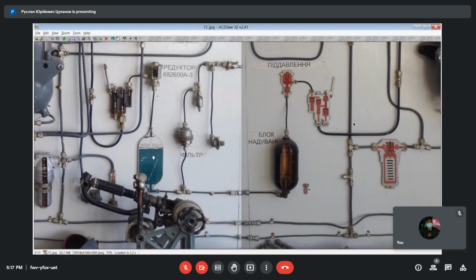It's like a source of high pressure air. Next, there is the pressure release valve, the actual structure with a manual handle, and a picture. The pressure release valve is intended to release extra overpressure to the atmosphere while the aircraft climbs to a higher altitude. Pay attention that we must provide a definite overpressure in relation to the ambient atmosphere.